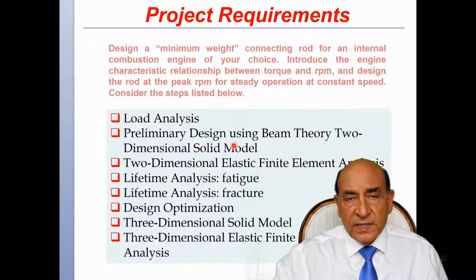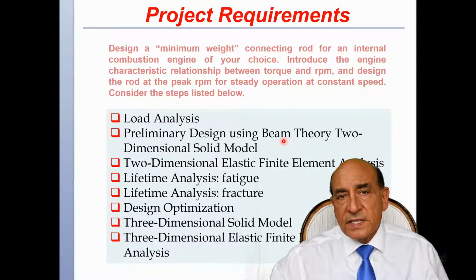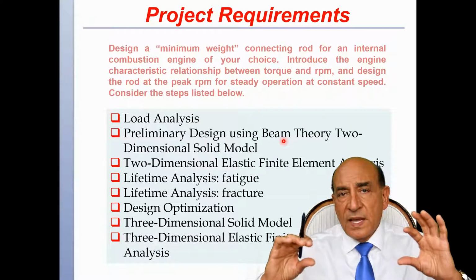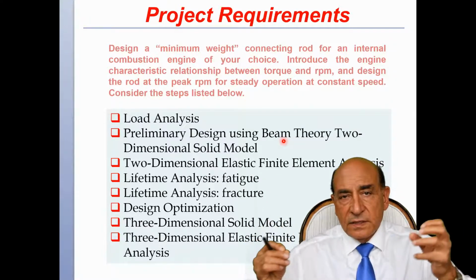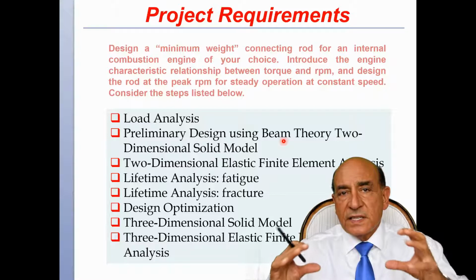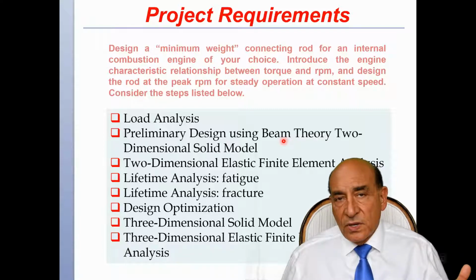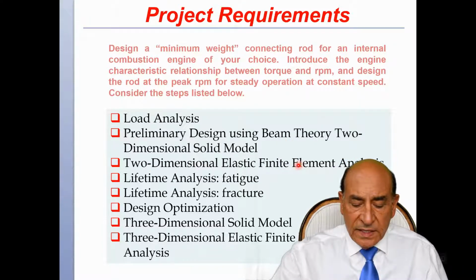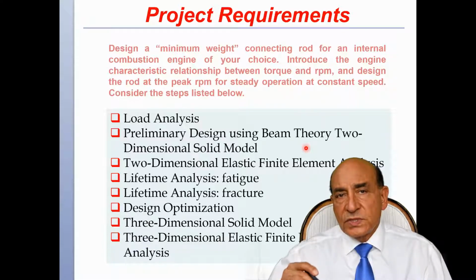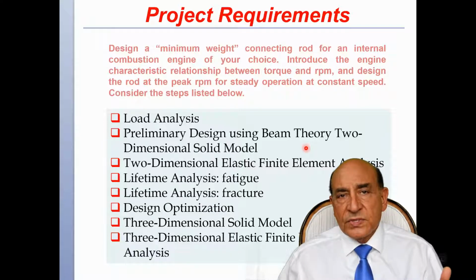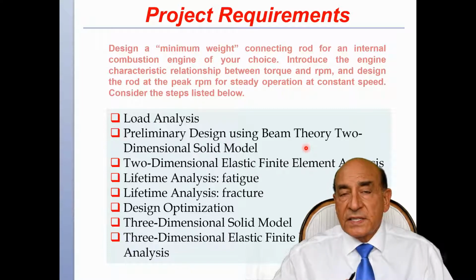And then once we have done that, we will take these forces and do a preliminary beam analysis. We can consider the rod as an ideal beam, and the ideal beam would have forces on all the different ends and inertial forces, and then we'll analyze it as a beam using beam theory, which we all should know. Once we have sized it by hand, which is an important step in design, hand calculations first, we should know the answer within, say, 30%. Once we've done that, then we can take it to the computer.